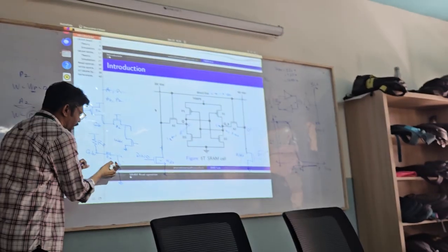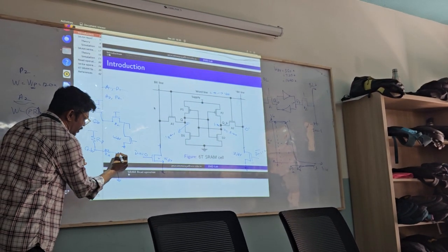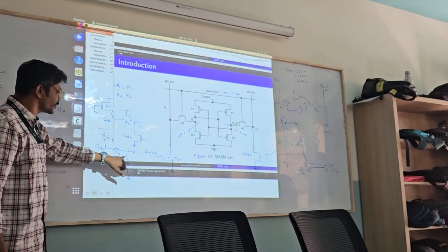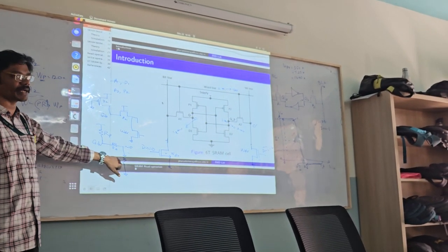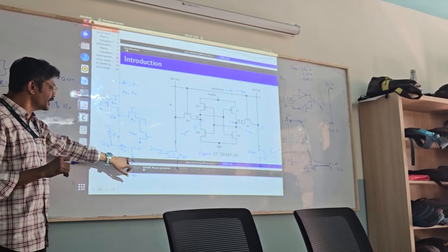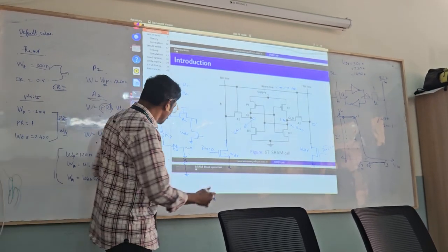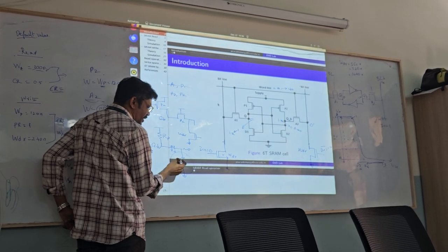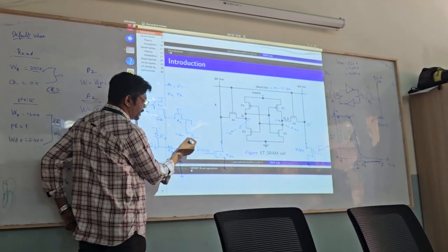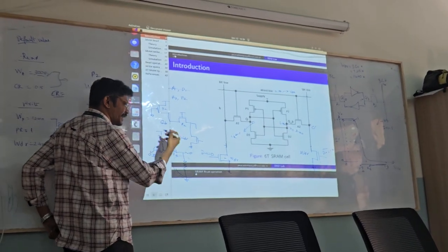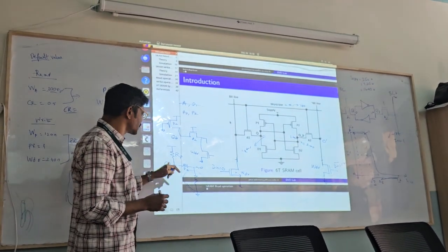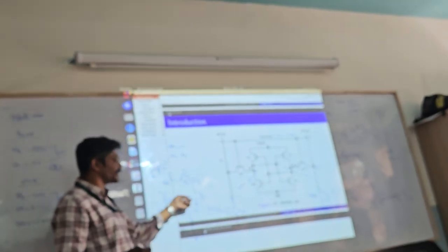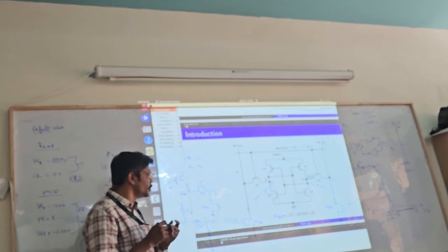Now this voltage is approximately close to the value of 0. It's not equal to 0, but rather close to 0. So here is where we have to worry about this WDR. It depends only on the WDR to ensure that I put this particular node voltage to 0.3. This means I need to consider the width of the driver circuit in order to perform this entire write operation. Not just the PMOS and the NMOS, but we also have to consider the write driver circuit as well. So we have two different variables.